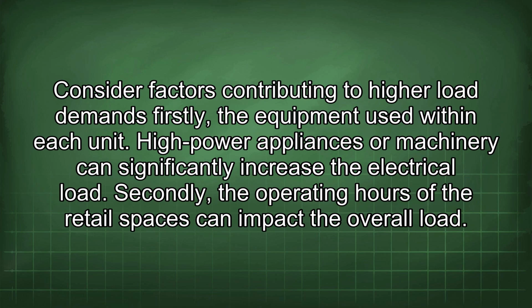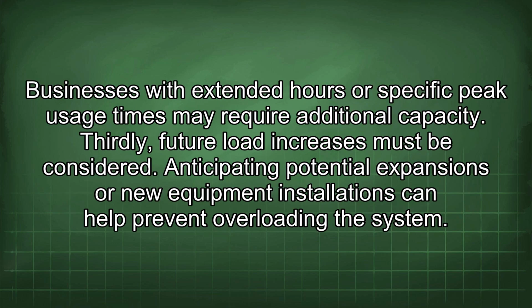Consider factors contributing to higher load demands. Firstly, the equipment used within each unit. High power appliances or machinery can significantly increase the electrical load. Secondly, the operating hours of the retail spaces can impact the overall load. Businesses with extended hours or specific peak usage times may require additional capacity. Thirdly, future load increases must be considered. Anticipating potential expansions or new equipment installations can help prevent overloading the system.